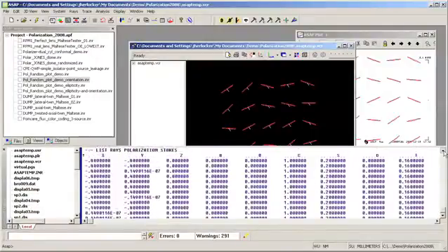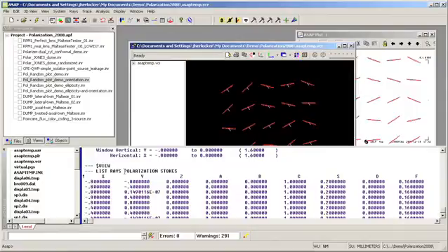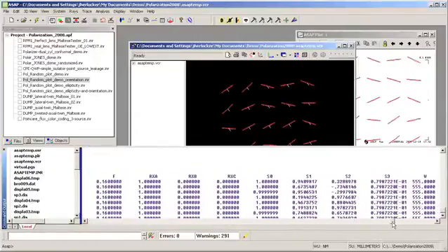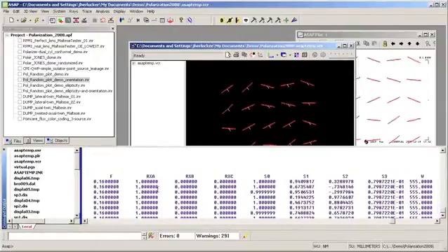List rays has been enhanced with a polarization subcommand and a Stokes option, and that means that we output with the list rays the polarization information in Stokes format. So in this case we have the reference polarization direction as a 3-vector and the Stokes parameters.